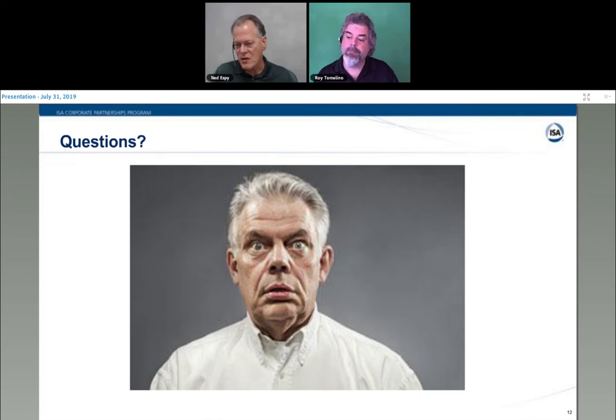And for the other things described, if you're checking multiple things, it's almost like the other question. If you can kind of validate, I'm going to use the word validate, that things are working in parallel, the DCS is getting the same number as the flow computer, then if you validate those things, you don't have to test them all the time.